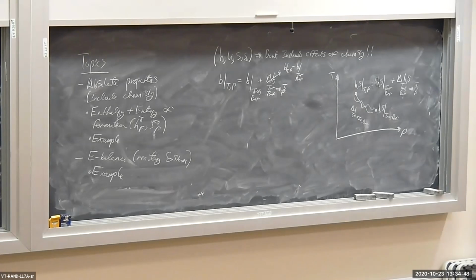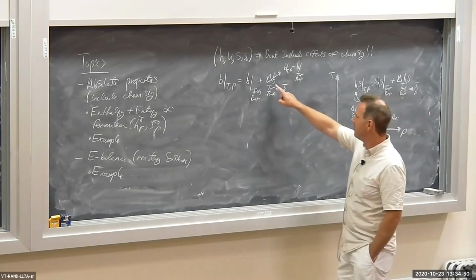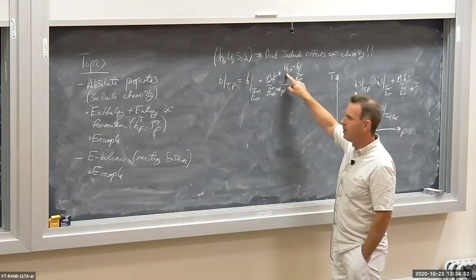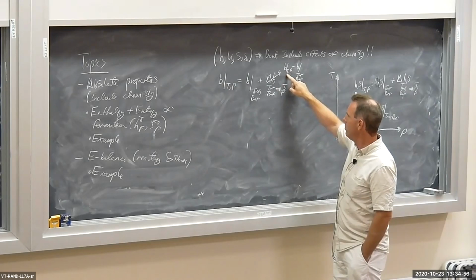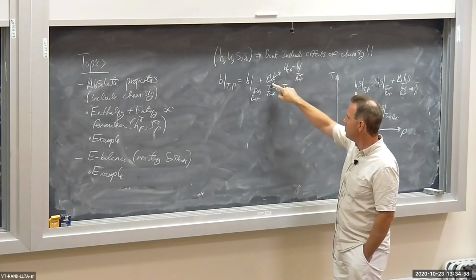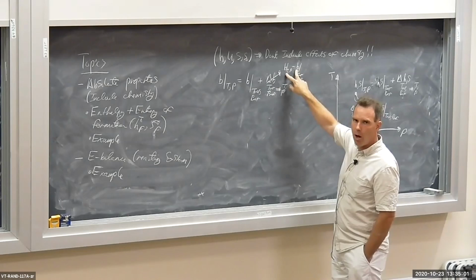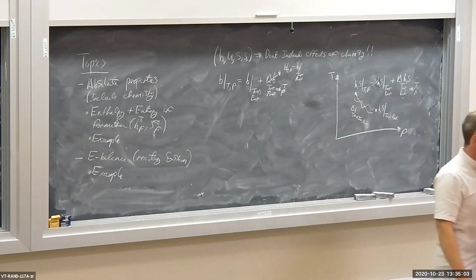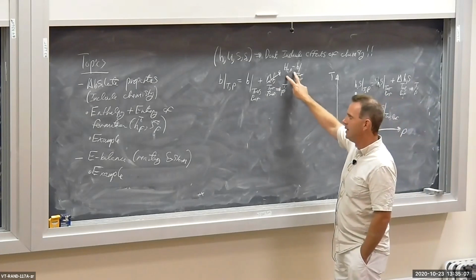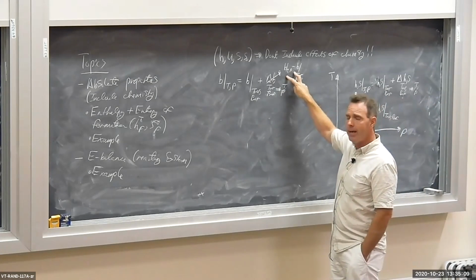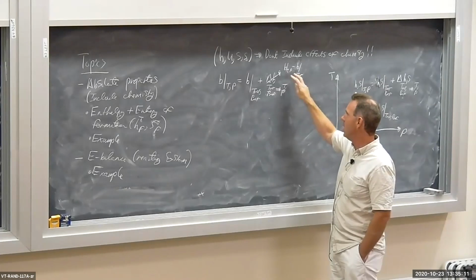So the betas in this delta beta term, where beta is some property, enthalpy, internal energy, entropy, need not include the effects of the chemistry. So we can look these betas up in our property tables, just like we've done so far up to this point in the class.